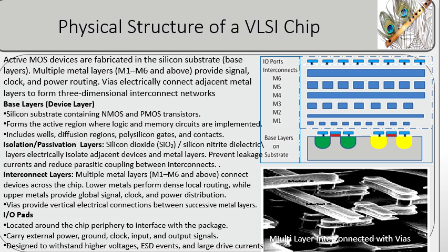Interconnects provide the physical connections between the various components of a VLSI chip. They carry signals between functional blocks, distribute clock signals, and deliver power through the power distribution network. The electrical characteristics are determined by the material properties and the structural dimensions.